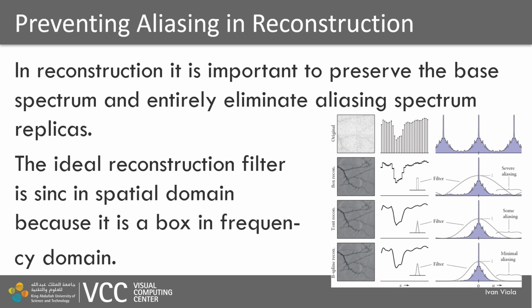So after we have performed band limiting or not, we have resolved our image in a certain sampling of our scene, and that corresponds to a certain frequency representation, with our signal being replicated several times in this frequency domain.